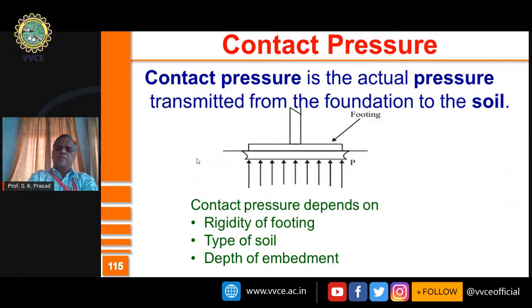Let us talk a little about contact pressure. As the name itself indicates, it is the pressure at the contact. Contact between what and what? It is the contact between the footing and the soil. It is the contact between the foundation and the ground below. So, the contact pressure is the actual pressure which is transmitted from the foundation to the soil.